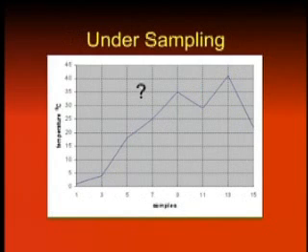The digital representation of the continuous signal only approximates the original signal and does not truly represent it, as can be seen by plotting the digital values. The reconstructed continuous signal does not give an exact replica of the original. The reconstructed signal has sharp edges and corners in contrast to the original signal, which has smooth curves.